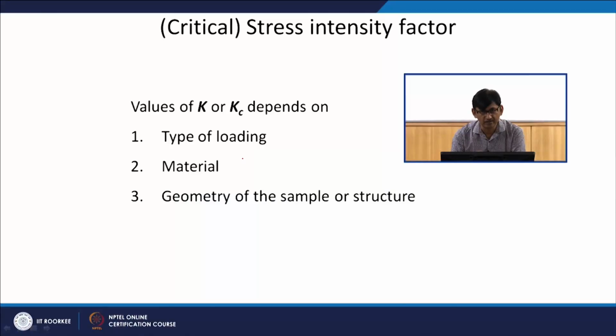Your value of K or Kc will depend on the type of loading, what type of loading I am giving, the material, so for each material I can find out the critical intensity factor, and the geometry of the sample or structure. So, what is the geometry of the structure. We will look into the detail of all these three parameters.